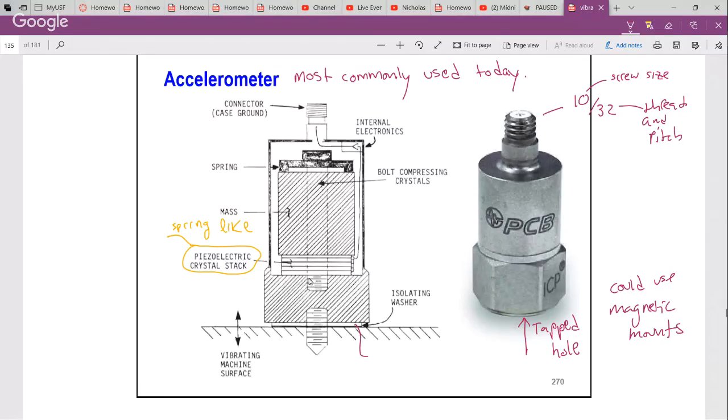So we put a ceramic washer in there. Why would you use ceramic? Well, it's good for compression. So it's good for compression. You wouldn't want to put anything soft in it, right? Why would something like CA glue, CA adhesive, be ideal? Because it's so thin and hard when it cures that it's almost like it's not there.